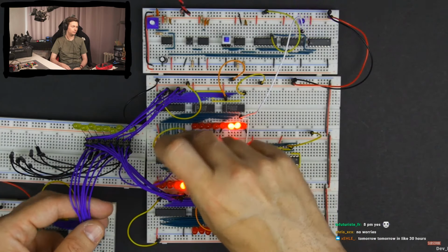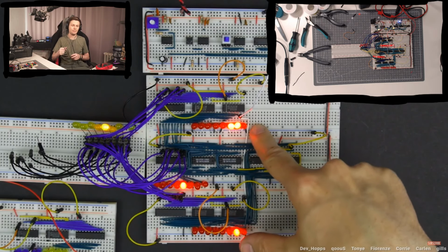You can see here, of course, this is only used for output from the ALU to the bus, because the ALU gets its inputs from the registers. So the inputs to the ALU, you have to load them into both the A register and the B register, and then it will either add or subtract them, and the output goes out to the bus here. So we can use this ALU output, or EO signal. If we take that low, then whatever's in the ALU, in this case an 8, goes out on the bus. Now, what we can do is read from the bus into the A register.